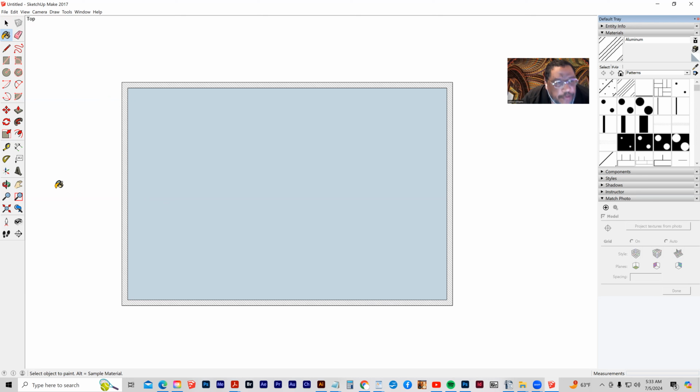Now, let's say we want to draw a room. I've got my pencil tool. I'm going to start down here and move upwards and find the middle here, midpoint. So that's 10 feet, but I can measure it as well and grab my measurement tool and drag up. That's 10 feet. All right. So I've got my pencil. I'm going to go up 10 feet from here, click and come in 10 feet, 10 apostrophe, enter. Then I'm going to drag down from there, 10 feet. And now I've got a room that's 10 by 10 feet, right?